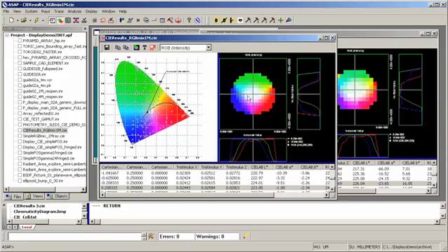With monochromatic analysis, we see that as just irradiance noise or intensity noise. With color systems, we actually see color noise on top of all that. So in this case, we have 3 little LED sources with some bandwidth, and we're depicting each of those with a finite number of rays, and more rays improves the situation.